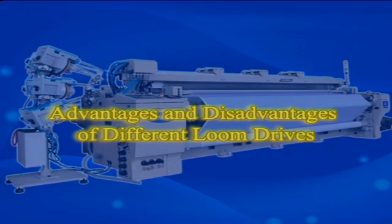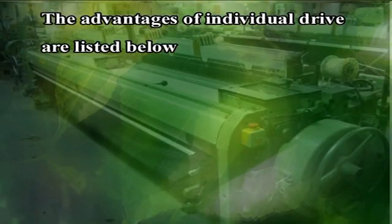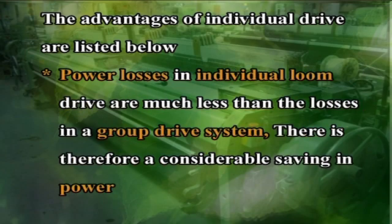Advantages and disadvantages of different loom drives. Coming to the advantages of individual drive, they are listed below. In case the motor of any particular loom fails, that loom alone will stop running while all the other looms keep running. Power losses in individual loom drive are much less than the losses in a group drive system. There is therefore considerable saving in power.